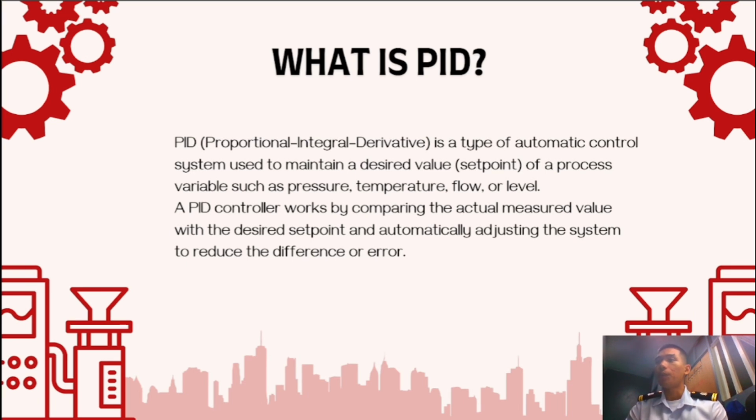The basic overview of proportional integral derivative control: a PID is an automated control loop mechanism that calculates process error, the difference between a measured process variable like pressure and the desired set point, and continuously applies correction to minimize that error.